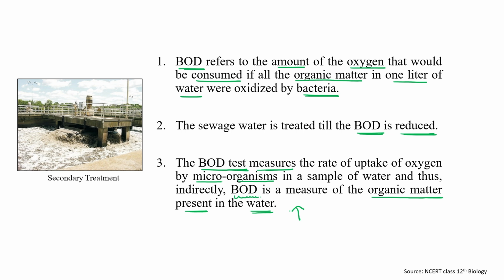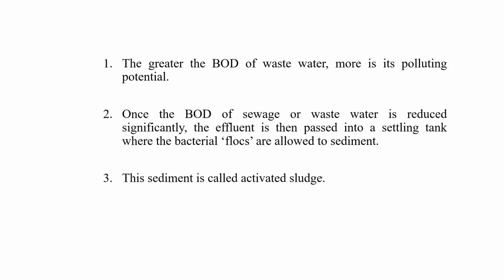At that time we can say that most of the sewage water has been treated by the bacteria. Clear? So this is a test which indirectly tells us the measure of the organic component present in the water. The greater the BOD value, the more polluted the water.